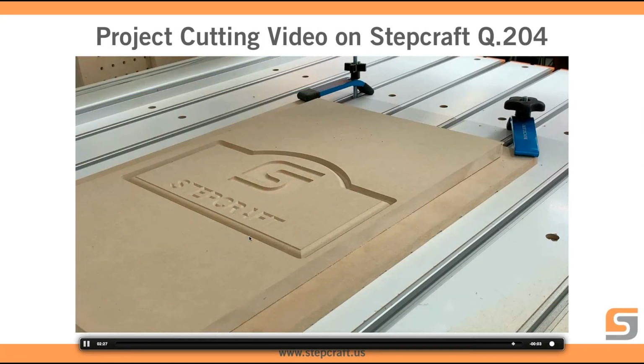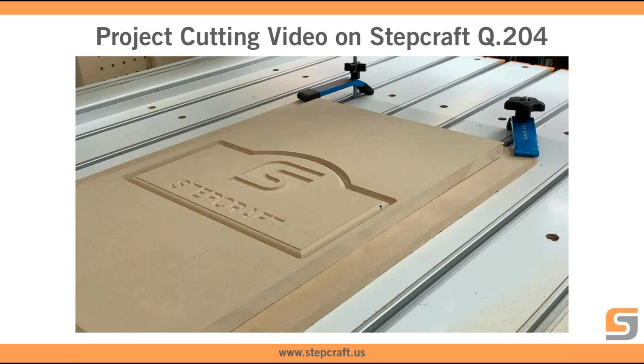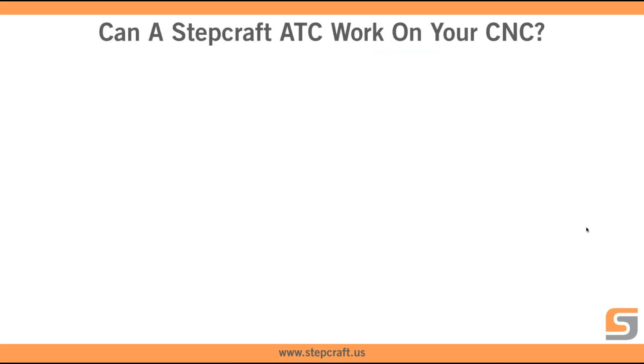But this is the finished project. Very simple, out of MDF. But you can see this is the reveal I was talking about. So I pushed this down, so instead of the roundover being even with the top, I wanted to have a straight lip around the edge. I just kind of like that effect. So that's basically what we're doing with the tool changer. It's really not that hard to set up the program.